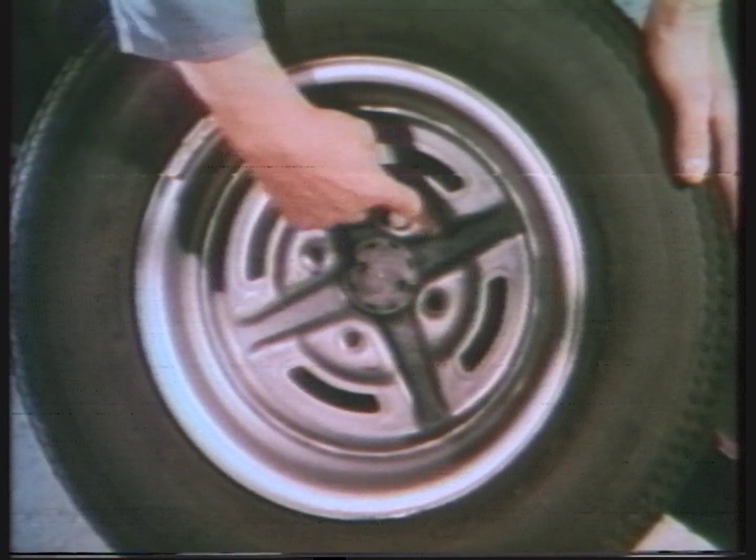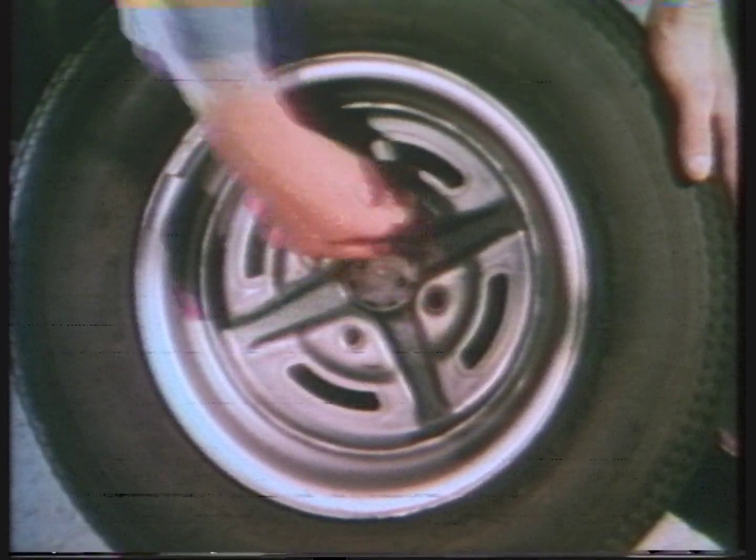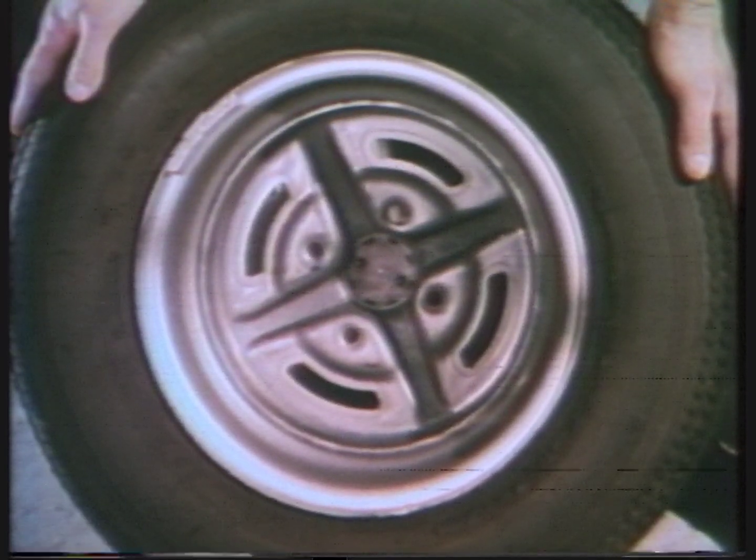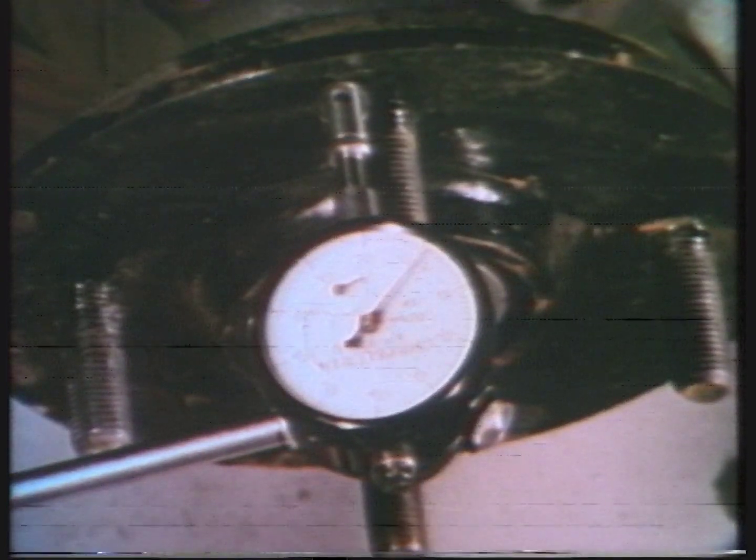Now examine the wheel mounting face for irregularities such as heavy, uneven paint runs or weld splatter. Anything that could force the wheel to run out of true on the hub. Check hub runout at the wheel mounting face using the dial indicator as shown. Zero end float is still maintained.